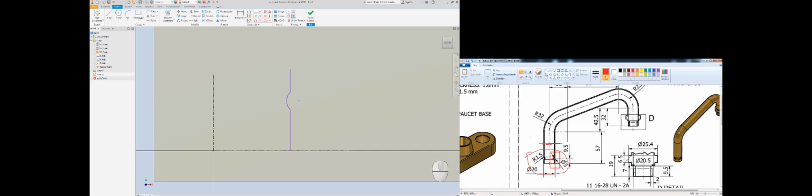We have a wall thickness, profile wall thickness at this point, which is 1.5. The radiuses are 1.5 millimeters. I will create an offset profile by selecting these two, make this one. Then I will close the ends in order to use this profile for the revolve process.